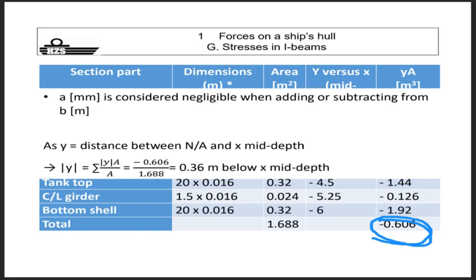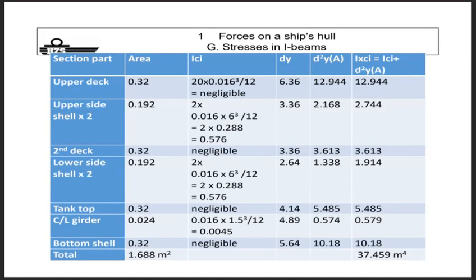If you have the position of your neutral axis, you can calculate the moment of inertia of the entire profile, meaning the moment of inertia of every individual element. And we always talk about plates, so it's easy. Its base times my height to the third divided by 12.